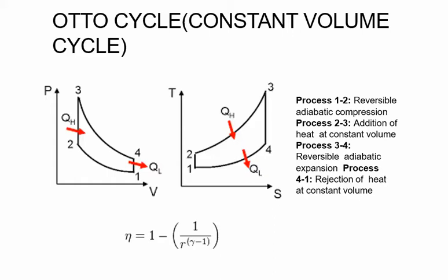Work is performed on the system during the lower isentropic compression process. The heat flows into the Otto cycle through the left pressurizing process and some of it flows back out through the right depressurizing process. The summation of the work added to the system plus the heat added minus the heat removed yields the net mechanical work generated by the system.